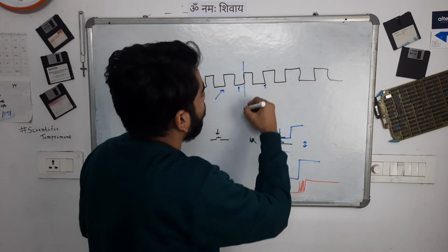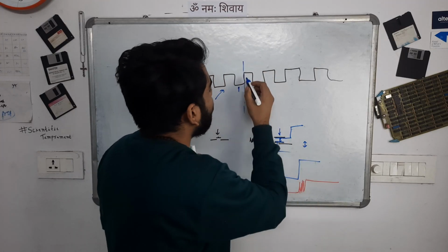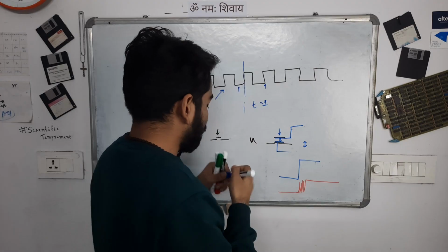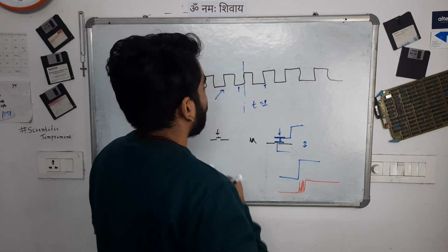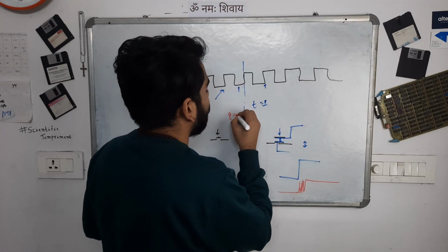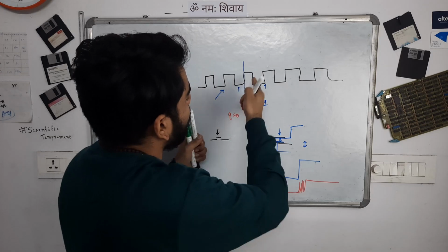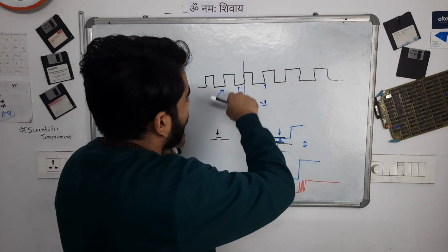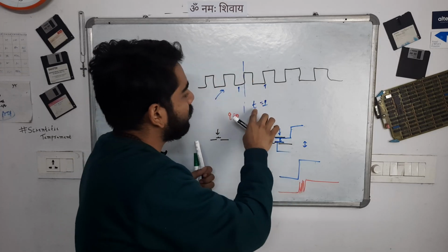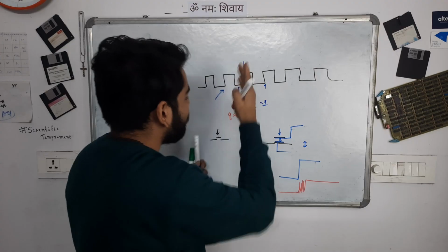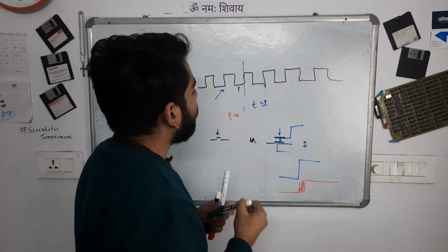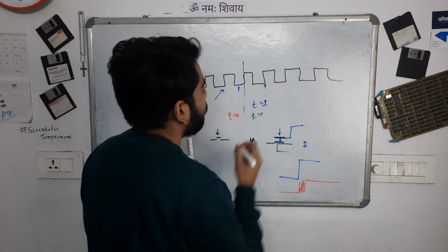This clock edge arrived, and toggling happened. Let's say the output q was 0 before this edge, and I pressed the toggle button, so t is equal to 1 at this edge, and therefore q will toggle and become 1.